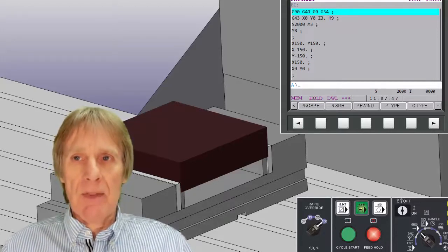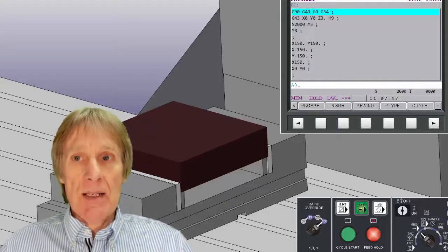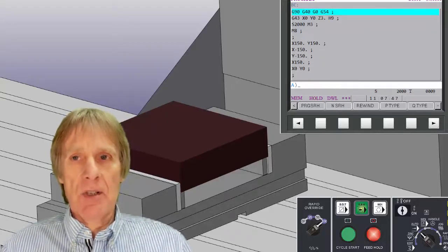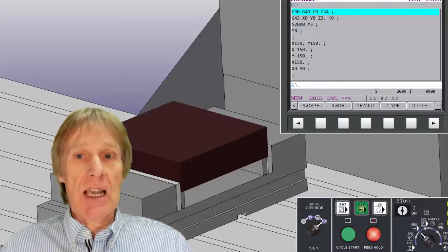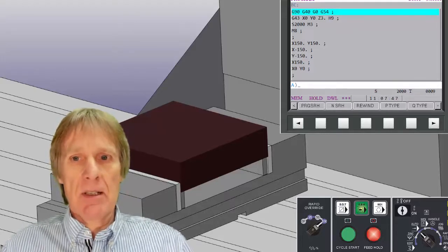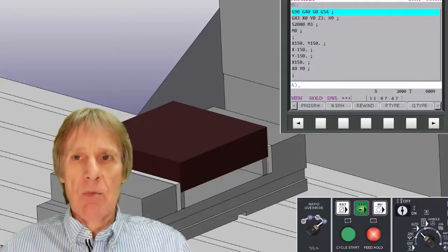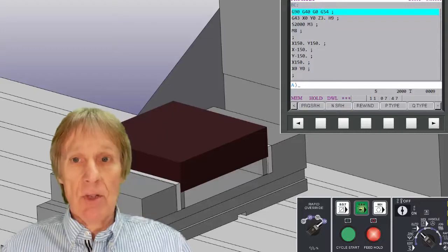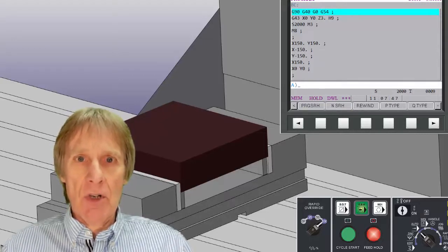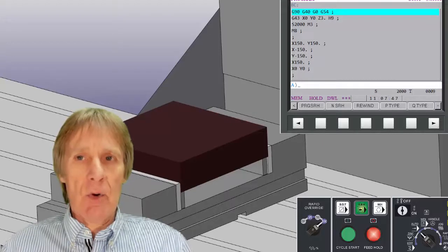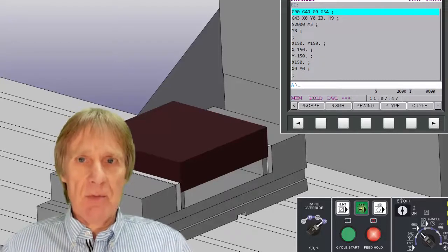So I'm going to talk about these 4 G-codes, and what they basically mean is G0 is a rapid command, which means the machine will move as fast as it can to a position, and G0 is just used to get somewhere effectively. So if we want to take a tool close to the workpiece, we use this rapid command, this G0 command, to get it there. And it will move all the axes together, so X, Y and Z can all move together on this, or you can move them individually depending on what you command. You can also command a 4th axis, like a rotary axis or even a 5th rotary axis.